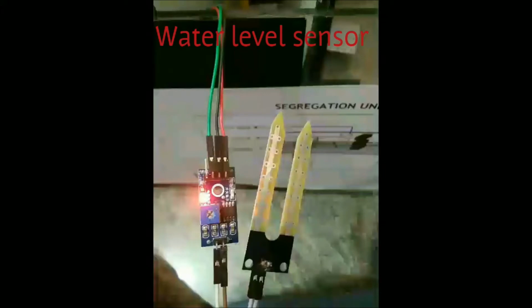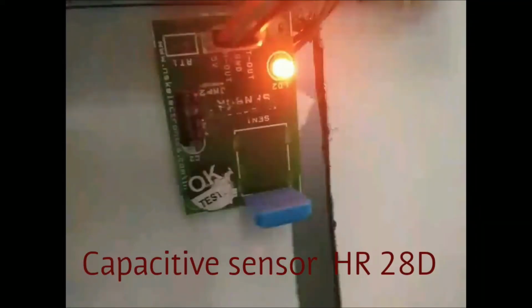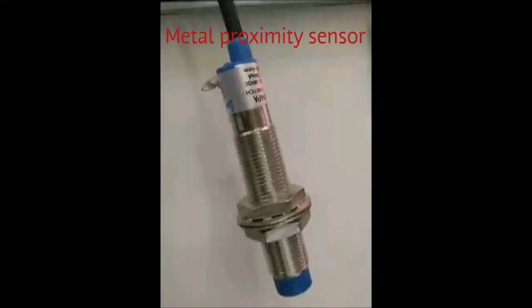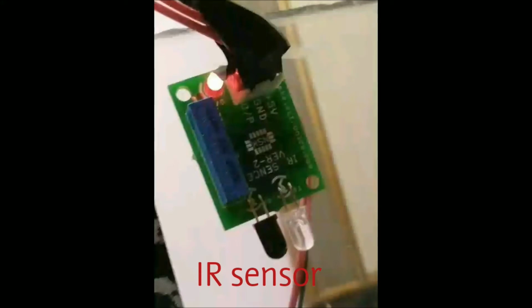The water level sensor contains 2 electrodes and is a digital sensor. The capacitive sensor is used to measure the amount of moisture present. It is an analog sensor which inputs values to the ADC of the microcontroller. The metal proximity sensor senses the presence of metal object and produces an output of 12 volts. IR sensor contains a transmitter and receiver which transmit and receive infrared rays. When there is any change in this, it produces an output of 3 volts.